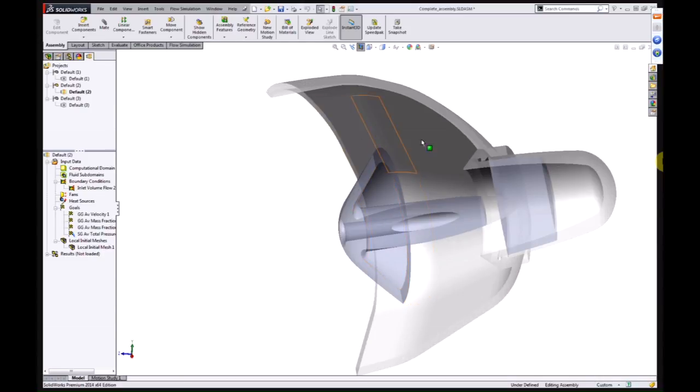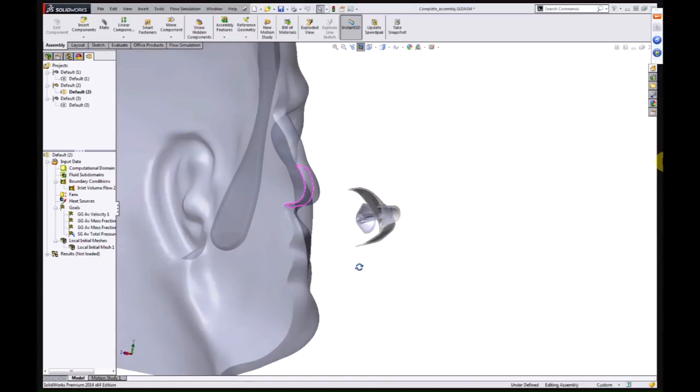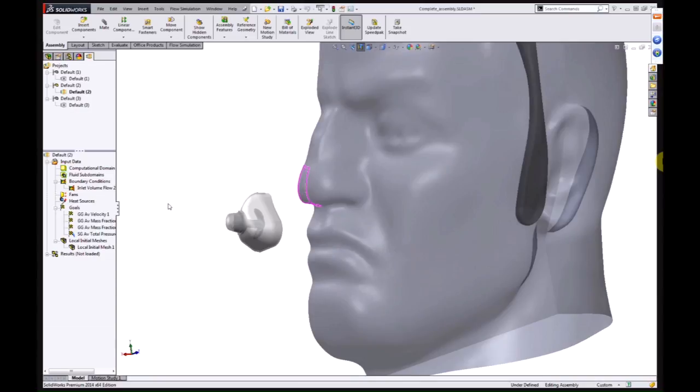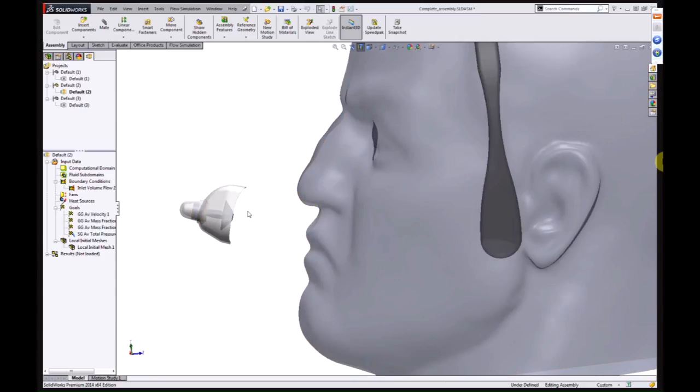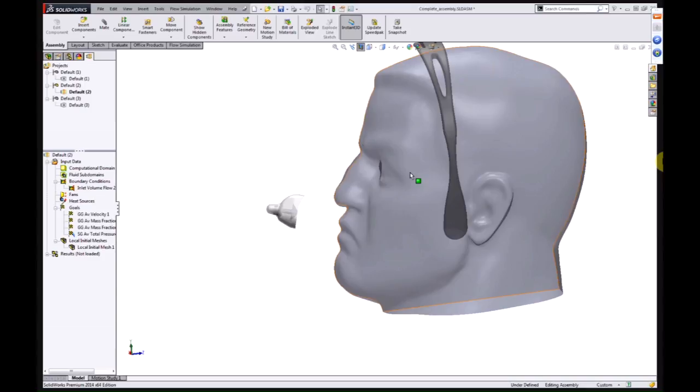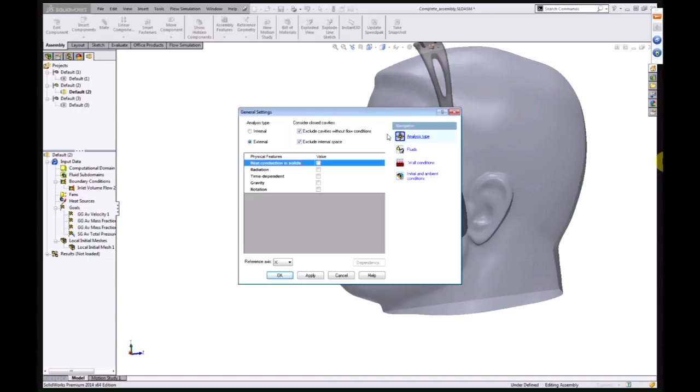And the setup for something like this is pretty straightforward in SOLIDWORKS Flow Simulation. Flow Simulation automatically knows where all the solid pieces of the model are. So we just need to tell it where to define the fluid region. We've identified a fluid region just by specifying some XYZ coordinates or push and pulling a box on the screen that encompasses the arm and the whole head.